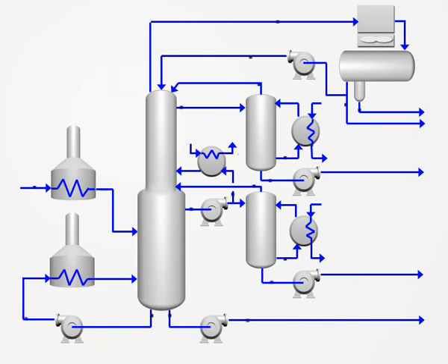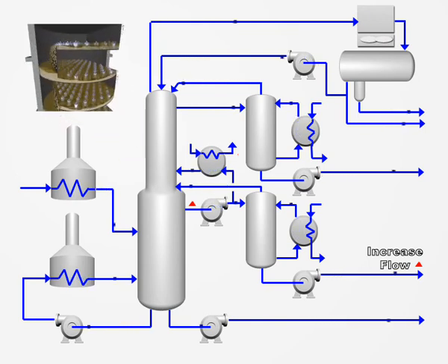This leaves us with the draw rate of the product. What are the results of increasing or decreasing the operational parameters? If the operator chooses to increase the draw rate of a side product, the following will result. As the liquid level on the trays decreases, the liquid-vapor ratio will change.